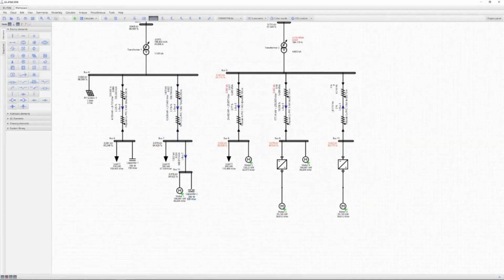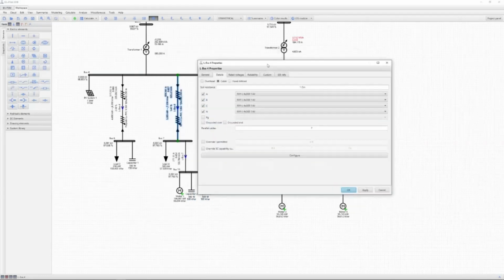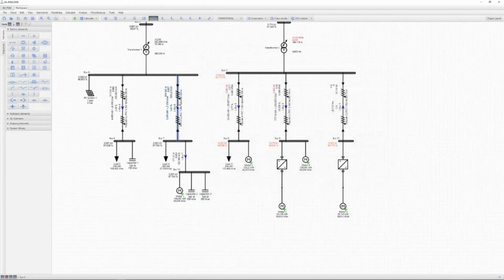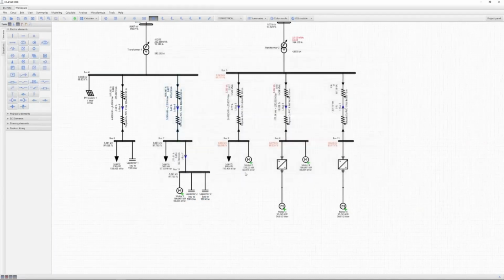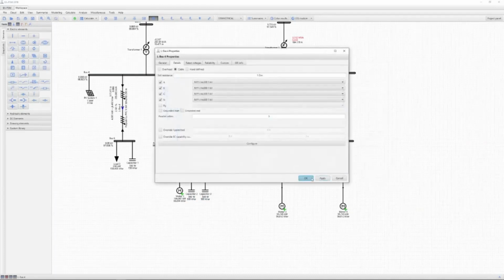See here, even more reactive power is still generated on our cable. That is why we still need to add more. Let's carry out the calculations again. And as we can see, if we compensate the reactive power enough, we can lessen the parallel cables in our scheme. Right now, even 5 parallel cables are enough. Let's check with 4. And still it's enough. Maybe 3 will be enough, but I don't think so. No, so let's stay with 4.